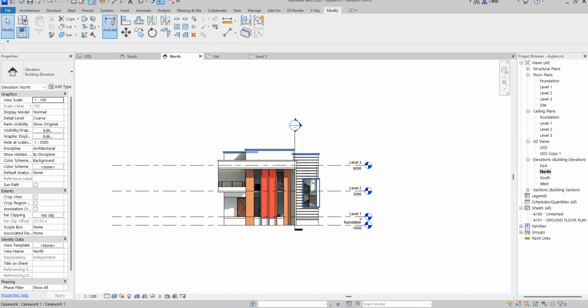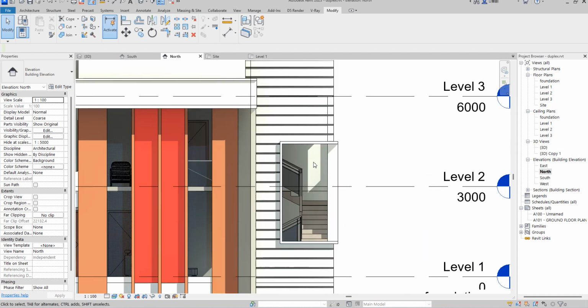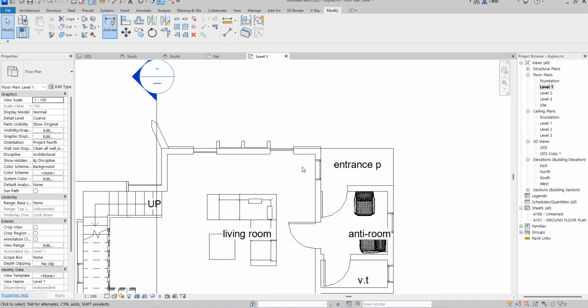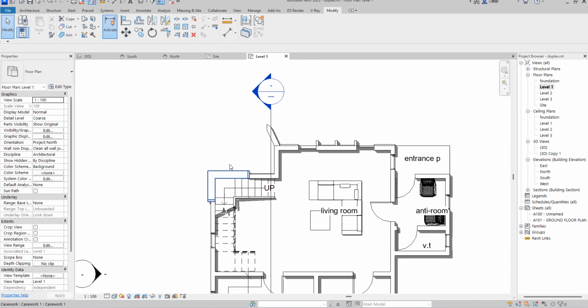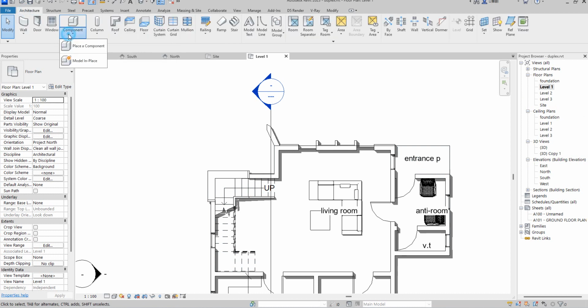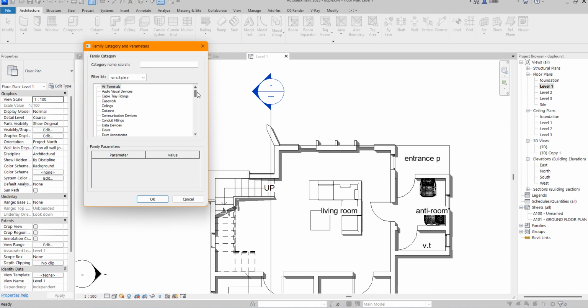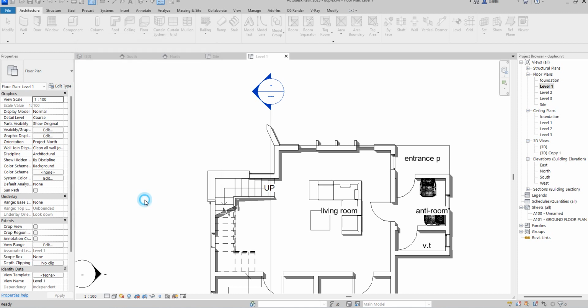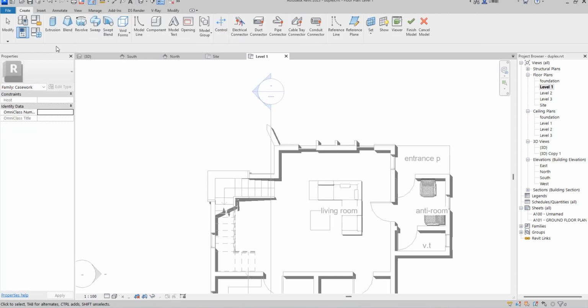So I'm going to start by, I've never created the parts. What I used to do, I don't normally follow, so just create the components and you free yourself from more issues. So what you do here is you just go to architecture, model in place, just come here, then select generic building and anything that you need. So casement will be the point of use. I will always advise you use casement to do whatever you want to do. So just change the material to glass and make use of it for that idea.